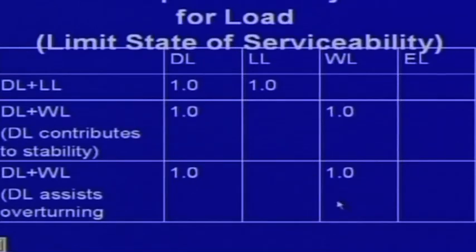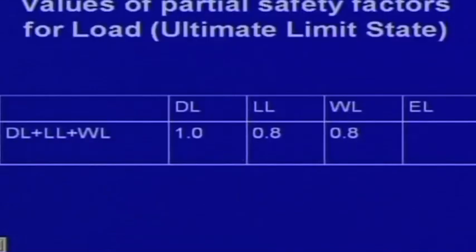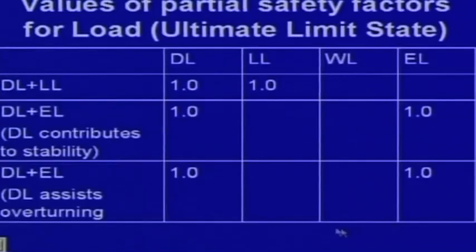And this is for serviceability. Whenever we consider serviceability, I mean when we consider cracking and deflection, at that time we do not multiply with any factor; we just simply take the same load. And this is for dead load, live load and wind load that we consider, and the other one when we consider earthquake load.